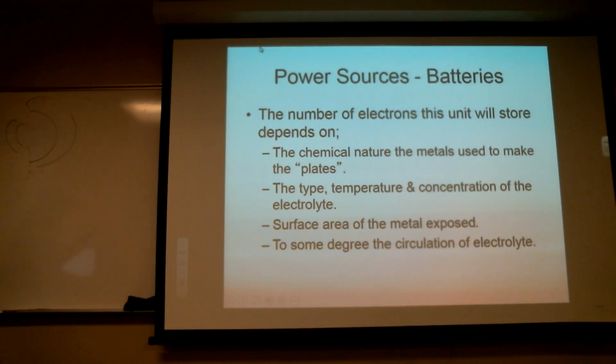Anywhere. Now, one of the things we're going to do is dissolve a bunch of sulfuric acid into the liquid, which is going to lower its freezing point quite a bit. But nonetheless, minus 57 degrees or whatever it gets in Alaska, really cold, beyond cold, below cold. Yeah, it can happen. It can shatter a battery. So one of the things you can do is A, keep it charged, and B, keep it warm.